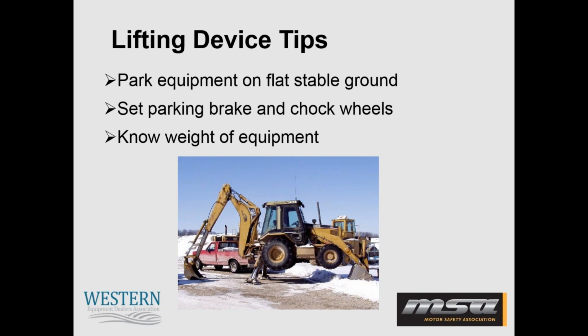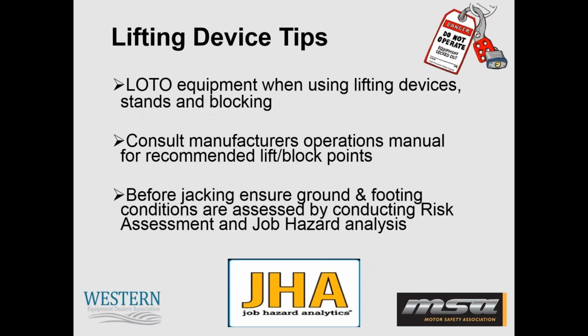And before you do any type of lifting, you need to know the weight of the equipment. And again, the operator's manual is a great resource for that information. Before you start lifting the equipment, you need to ensure that equipment has been locked out and tagged out before utilizing any stands or blocking. And just on a side note, if you are looking for lockout, tagout information, in the past I have completed a webinar which is on our website, which goes over some of the lockout, tagout practices, as well as some procedures. So check that out if you need more lockout, tagout information.